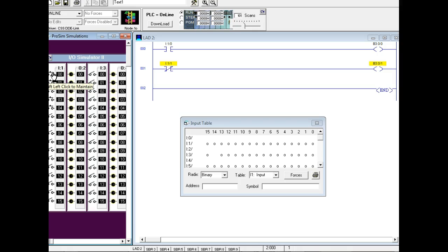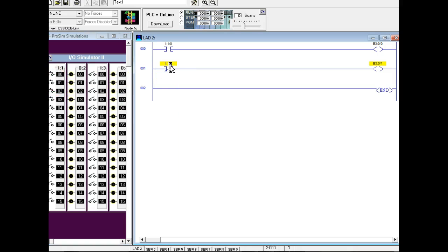When I say true or false, which is what your PLC program is looking for, what's the truth? Whatever the program looks for. And that's what you're doing when you do examine on and examine off. You're changing the meaning of a true and a false. Y'all understand that? So right now, this guy right here is set up as a normally closed. And I can't see it, I'm going to have to go offline.